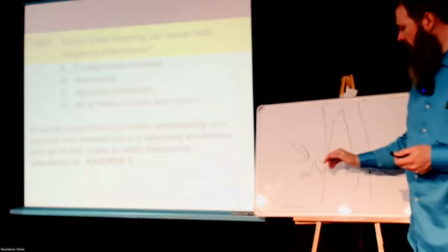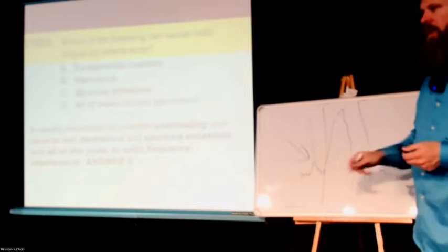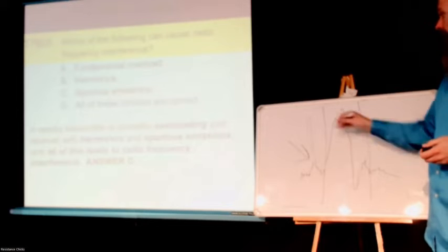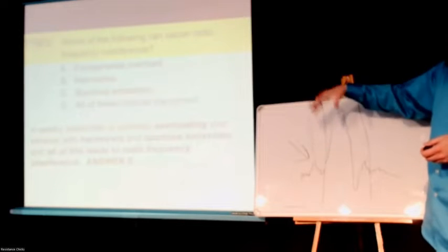They're obviously much weaker than the signal that's up here. They're clear down here. They're little spurs. If my radio is designed very well, these spurs are quite low and do not cause interference to anybody. But if the radio is cheap and designed minimally, sometimes these spurs can be quite large. And they're causing interference outside of the frequency that you are intending to transmit on.